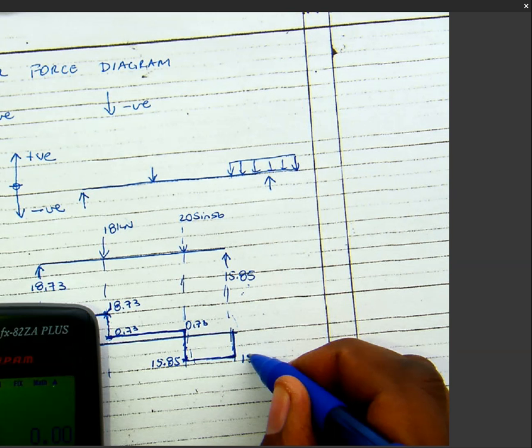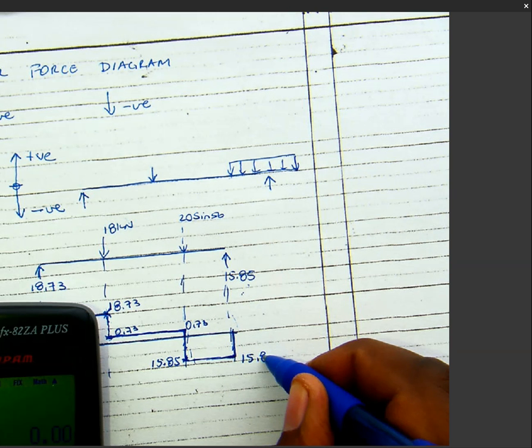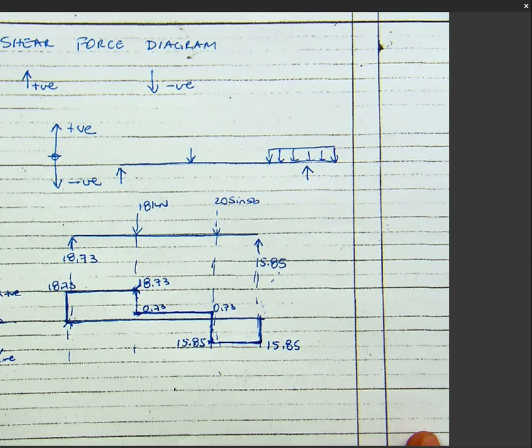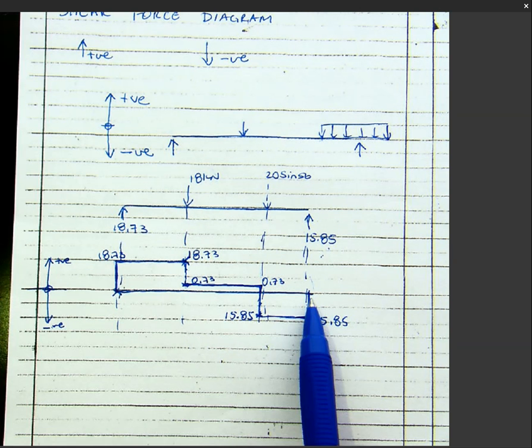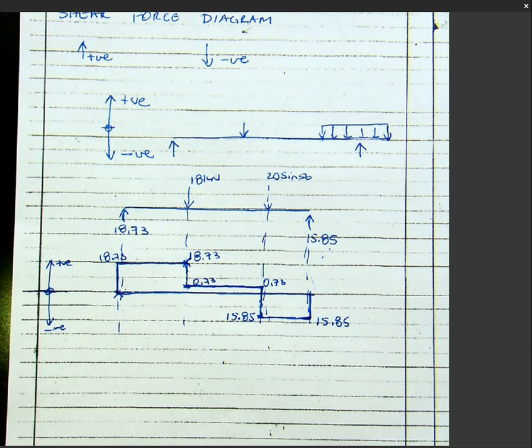Very important, guys. You always start at 0. You must always end at 0. That's how you must approach the shear force diagram. I hope we're happy.